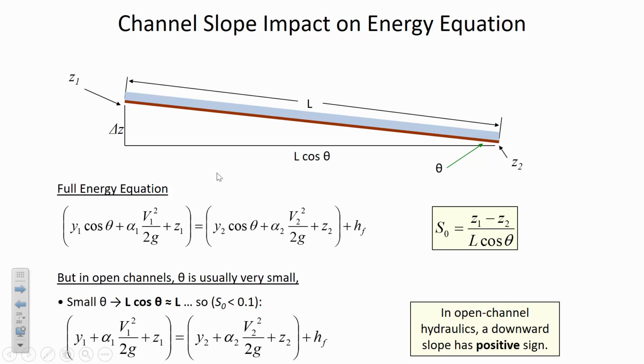But down is considered positive for a slope. So when I say a river is on a 1% slope, I don't mean that the river is going uphill at 1%. It's just taken as a given that a negative slope is described in positive terms. So we don't bother putting the minus sign when we talk about the slope of streams or sewers.